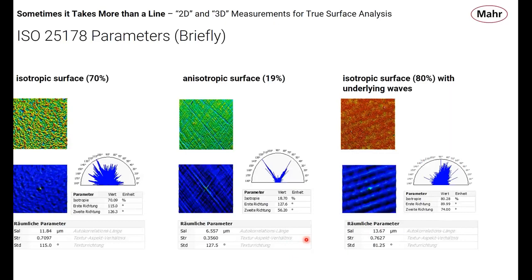If that were 1, it means that there is no aspect to the texture. It's even in all directions. Not necessarily isotropic, but the texture directions we find are even. But here it says no, actually. Indeed, those northwest to southeast honing marks are actually a stronger signal than the southwest to northeast. So these honing marks do give us a stronger signal than these honing marks.